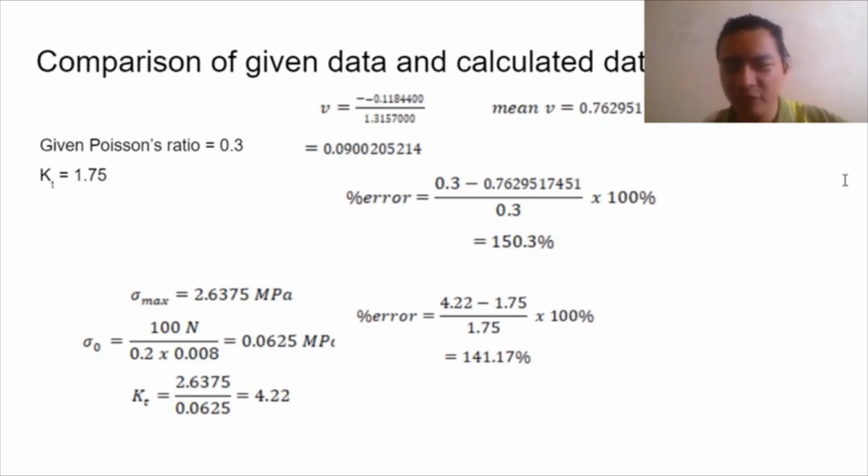Therefore, it is important to carry out analysis with plus or minus a few elements near the chosen number of elements to obtain a better result. In conclusion, a higher number of elements generally produces results with higher accuracy, but to make sure the elements are not distorted due to their number, analysis with a fraction of elements fewer or more needs to be done.